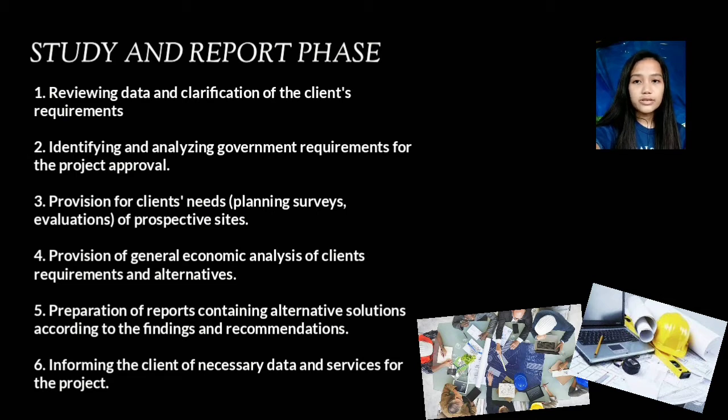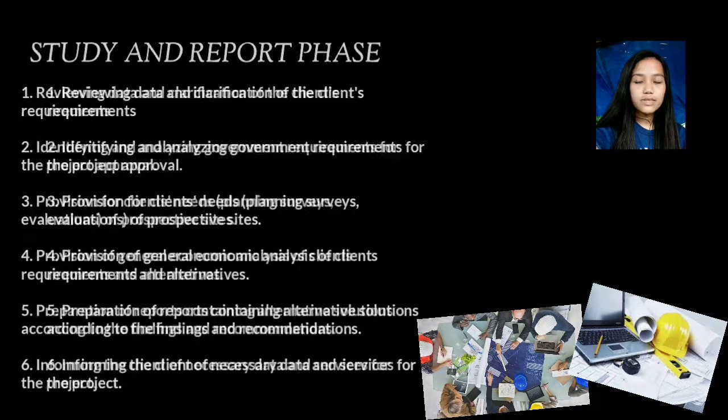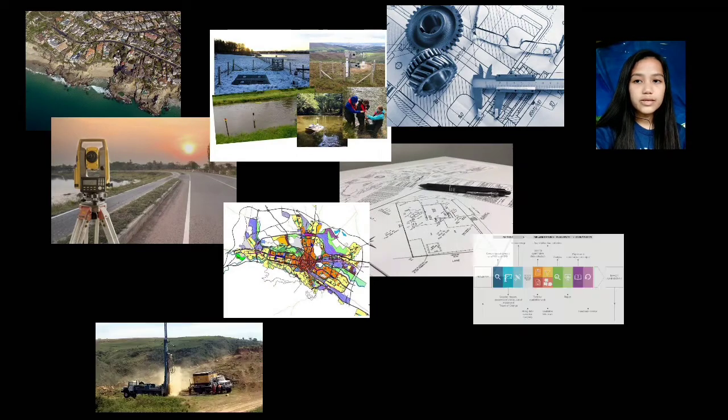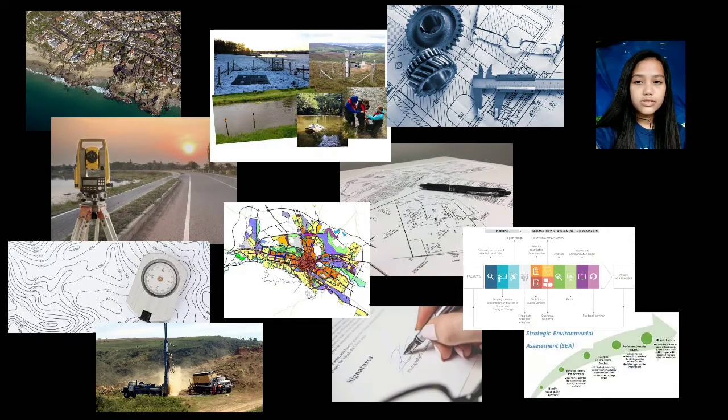When starting a construction project, you will have to determine its feasibility by evaluating its pros and cons. In this phase, you will have to consider the objective and requirements of your project, as it can be an opportunity or a problem for you as a builder. Such necessary data includes photogrammetry, reconnaissance survey, property surveys, topographic surveys, geotechnical investigations, seismicity studies, hydrological data, traffic studies, materials engineering, zoning assembly, land use information like deeds, environmental assessment, and impact assessment.